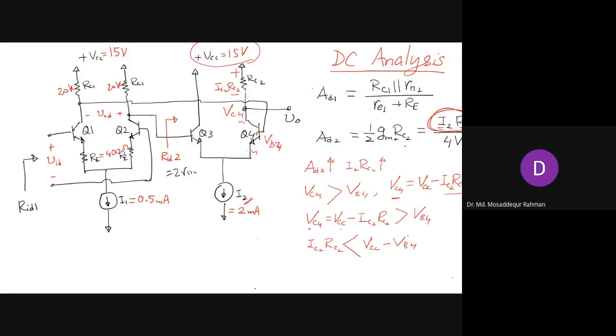That sets the limit for how high you can go for this parameter. It also sets the limit on how high you can set the gain of this amplifier, because the denominator is a constant, about 0.1 volt or 100 millivolt. So this sets the upper limit for the gain of the amplifier.